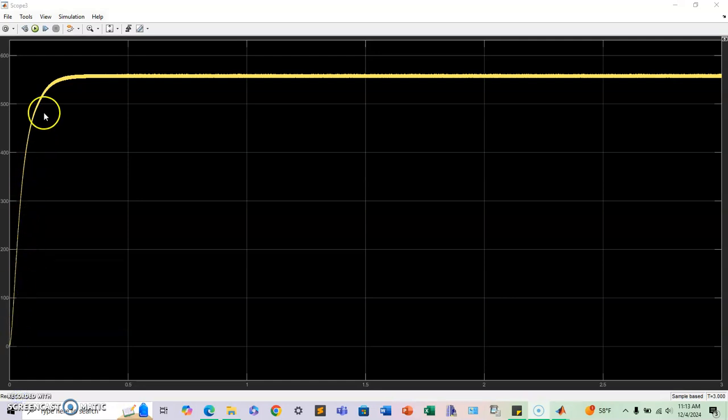See how it shoots, but it has no overshoot. The controller has a really smooth shape to it, and we also have very small ripple. That's actually behavior that's desirable in a battery backup, and not only because of the limitations of the equipment that are already there. So if you have a capacitor bank or a battery backup, you can actually not throw all that voltage to waste. That voltage is not going to be good enough to generate the power on your three-phase load, but you can actually save it right here.